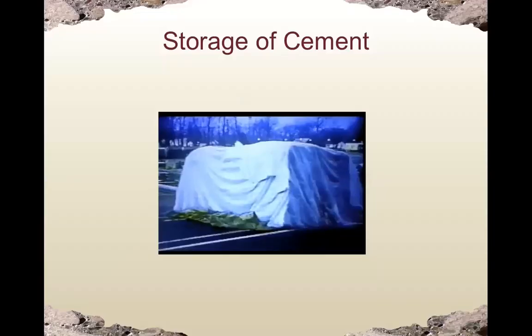Waterproof coverings should fit over the pile and extend over the edges of the platform to prevent rain from reaching the cement and platform. Cement powder is very sensitive to moisture, so we need to keep it 100% dry before we use it. Otherwise the fine particles of cement will stick together. The typical size of a cement particle is around 10 to 20 micrometers. When there is moisture in cement, the fine powder will stick together, which reduces the efficiency of cement. So keep it dry during storage.